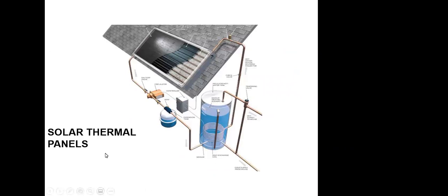And then you need to connect this. We have exactly a hydronic system. It's always the same. We have something that heats up water. In other cases, it's a boiler or turbine, whatever. In this case, it's a solar panel. And then we have a supply and return or inlet and outlet. We always have the expansion tank. We always have a circulation pump. And in this case, we need a tank. So we have a tank here.